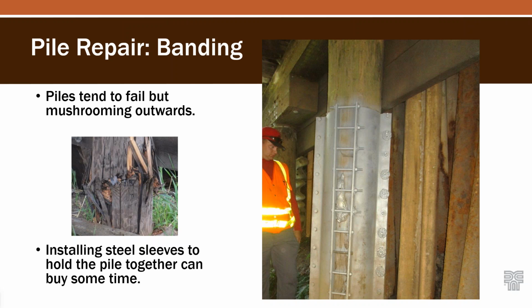It doesn't necessarily drive up the axial capacity from a calc standpoint because you'd still have basically whatever remaining good section you have, but it's pretty easy to install. So this is a fairly nice banding system where they split some steel piles up and then welded some tabs to it so they could basically make 4 pieces and clamp it on to help confine it. And it's just another tool in the toolbox as you try and extend the life of these bridges. But again, on this one, I would likely consider it a temporary repair.